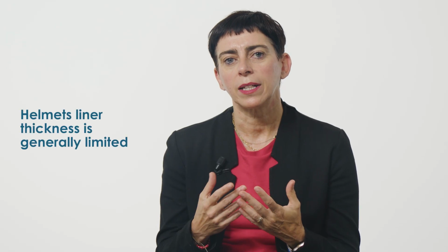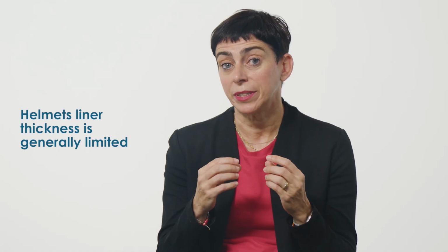Designers have limits for the thickness, as overly large helmets are uncomfortable, and in addition they can increase rotational acceleration by increasing torque applied to the head, which generates harmful rotational deformation of the soft brain tissue. As such, helmet liner thickness is generally limited. So, combining layers of foam of various relative density and hence stiffness may broaden the range of manageable impacts.